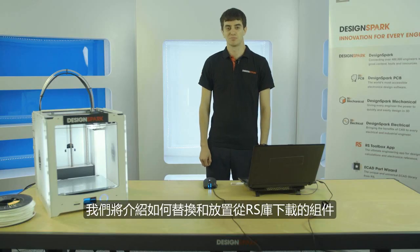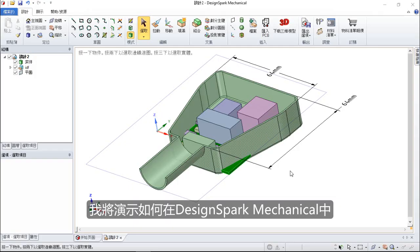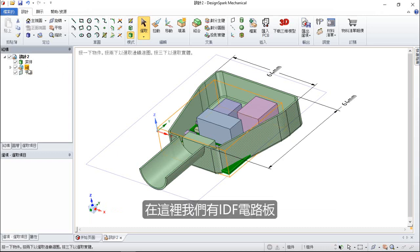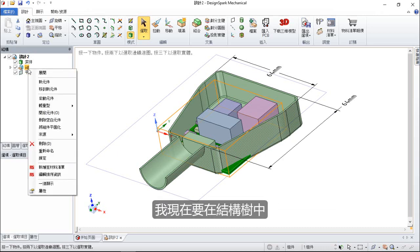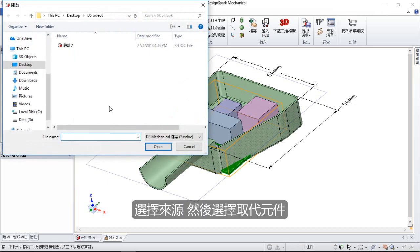Next we will look at how to replace and position components that can be downloaded from the RS library. I'm going to demonstrate how to replace components in DesignSpark Mechanical. So here we have our IDF circuit board. I am now going to replace this circuit board by right-clicking on the IDF in the structure tree and selecting source and then replace component.